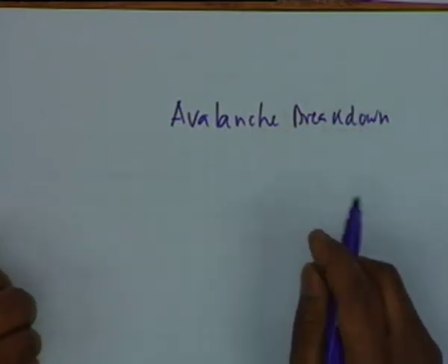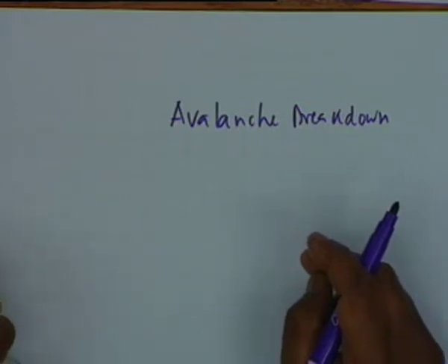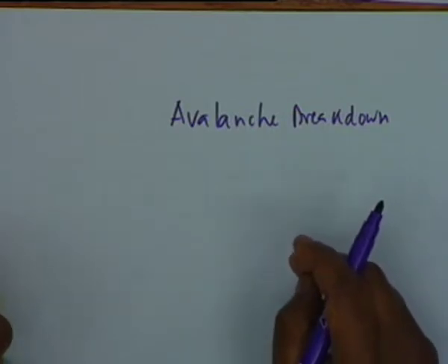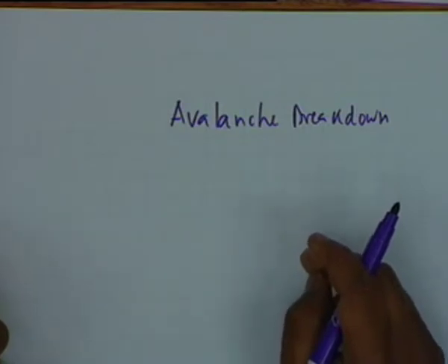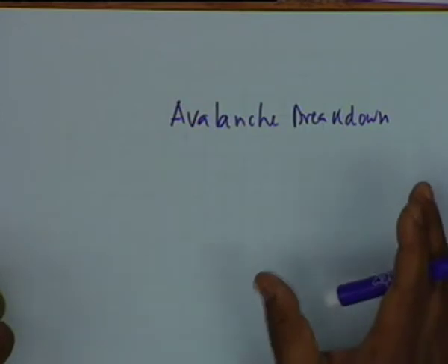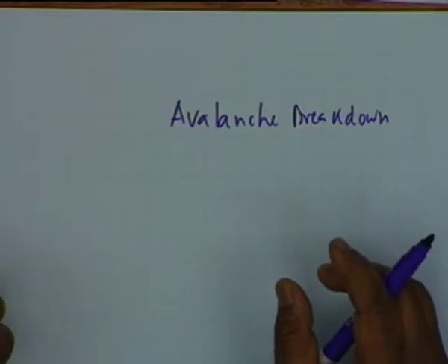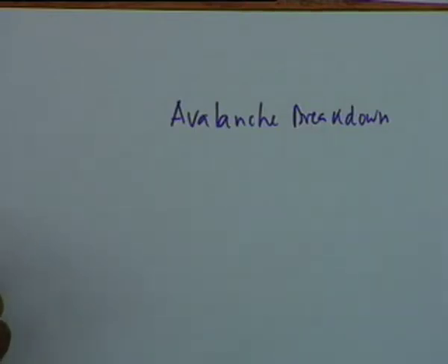The only thing to be remembered is that Zener breakdown occurs due to electric field in a material in which there is relatively heavy doping. Avalanche breakdown occurs due to actual collisions of high energy particles with fixed atoms, and can occur even in lightly doped junctions. In practice, when a breakdown occurs in a diode, it is usually a combination of both, the electric field and high energy particles.